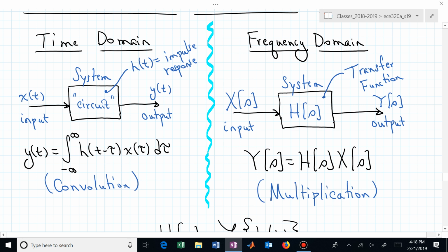So we throw all of our circuit pieces into the frequency domain. We analyze the circuit in the frequency domain. We end up with a voltage. That's maybe what Y of s corresponds to. And we want, what is y of t? What's that look like in the time domain? Then we simply do the inverse Laplace and find out what that voltage is in the time domain.